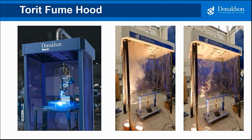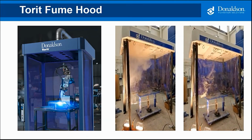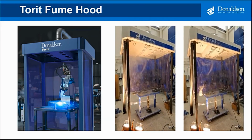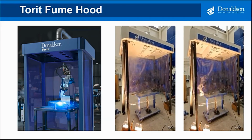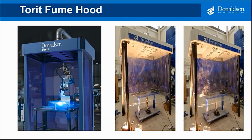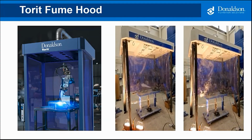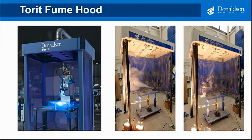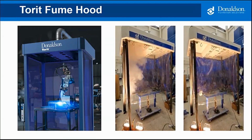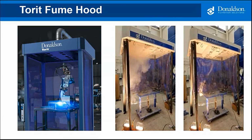You also notice that it has a canopy around that. So the air is now pulled in from the bottom, and it works upwards past the part up to the top, and then the smoke disappears. So here we have a properly designed hood with the right amount of air volume. As you see, none of that smoke is getting outside of our canopy hood.